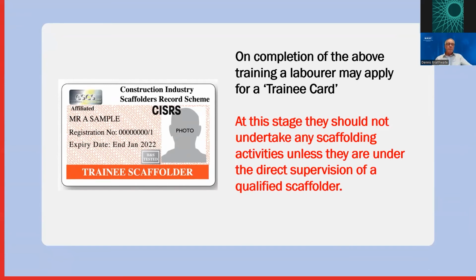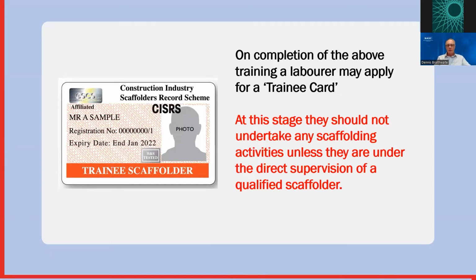And as I say, he's basically a trainee scaffolder. At this stage, he shouldn't undertake any scaffolding activities unless he's under direct supervision of a qualified scaffolder. So he can work on the scaffolding, but he shouldn't be taking anything on his own. He shouldn't be allowed to work at height unless he's under supervision.